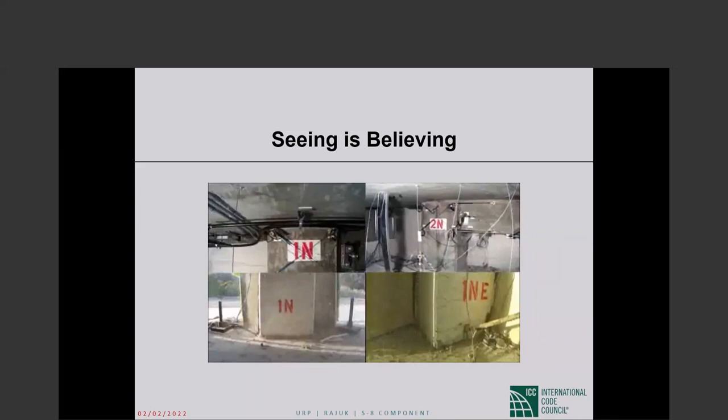The response modification factor of the superstructure will not change. It will be what it is. What you will be doing is cutting off the ground motion, so the motion transferred to the structure will be very different. So I would hesitate to call it damping either.